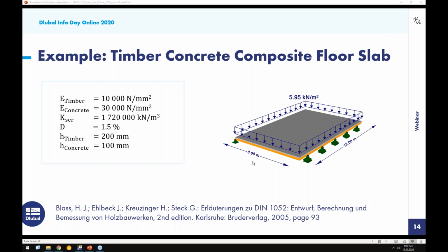Okay, so I made a video, but unfortunately it's only in German because of beam elements. But today we talk about surface elements. So we have a laminated timber ceiling, so not a cross-laminated timber, it's only a laminated timber ceiling. So we have no stiffness in this direction. And on top we have some concrete, and we connect the concrete to the timber somehow.